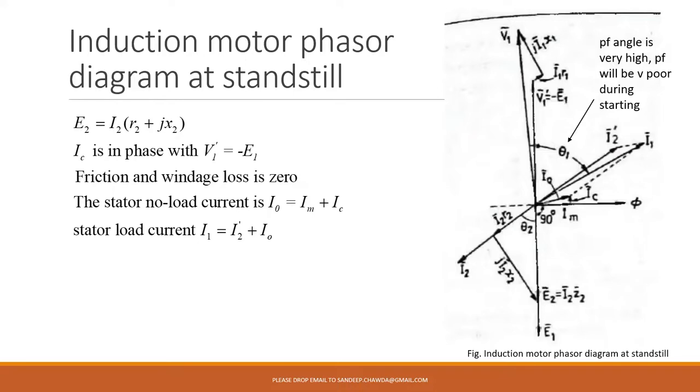So when you have a higher angle, the power factor is poor. So during starting or standstill condition, the power factor would be very poor. This is one of the features of the induction motor. So whenever you draw the phasor diagram for starting or standstill condition, you must keep in mind that the angle should be wider. So this is the phasor diagram under standstill condition.